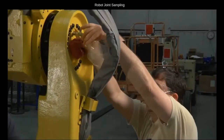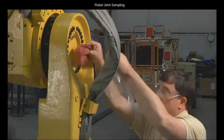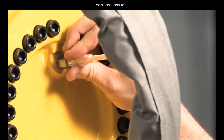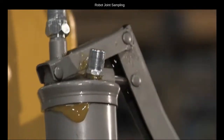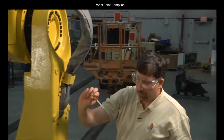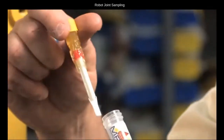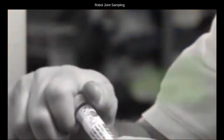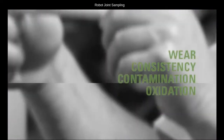We remove the clear plastic body and bag and insert the Grease Thief into the adapter in the purge hole. We add only about 2 more pumps of grease to fill the sampler. The Grease Thief sampler is then removed from the purge hole and capped and sent to the laboratory for analysis, where it can be evaluated for wear, consistency, contamination, and oxidation.